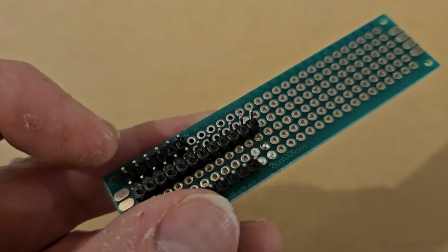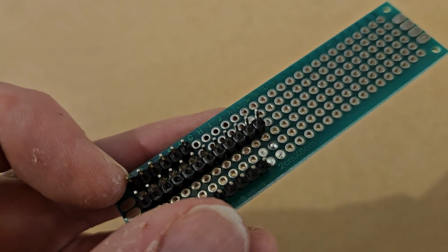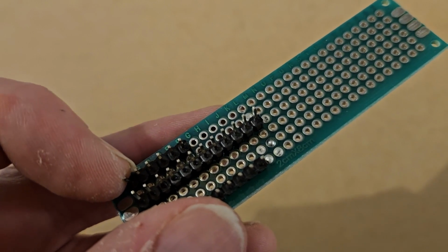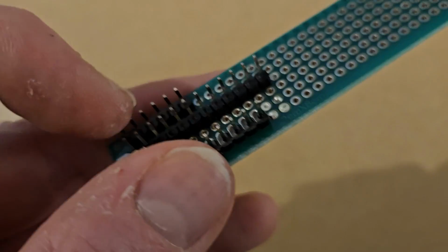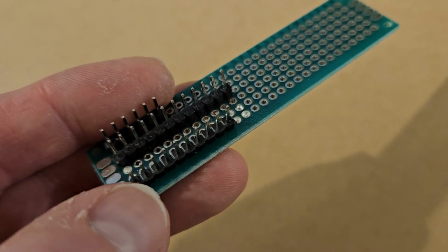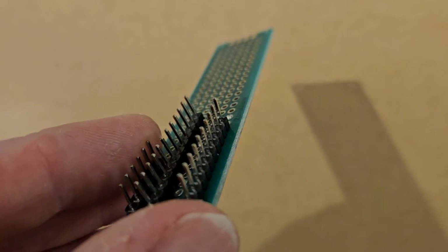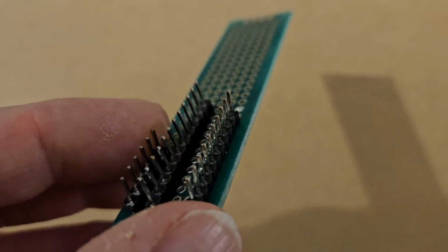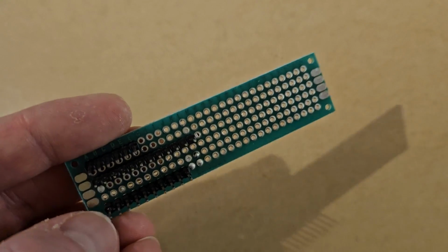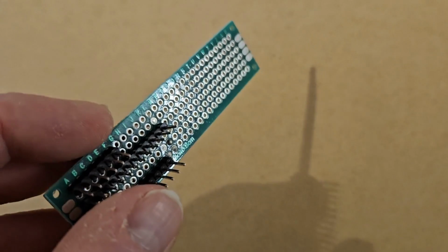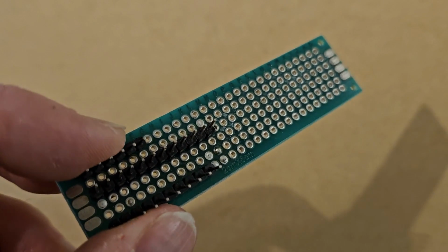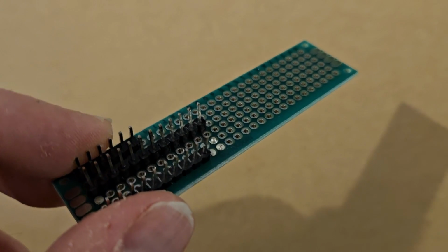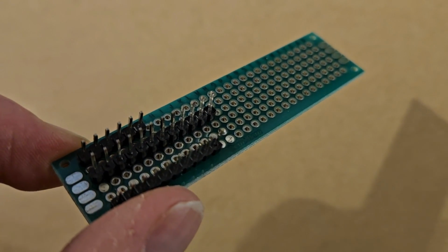And then the idea is this is the 5 volt input, so one for input, one for the screen, one for the ESP and a few spares, a run of grounds along the middle, and then the 3.3 volt shared on the bottom. And this is small enough to just screw into the inside leg of the knob box and keep itself out of the way, but fixed and steady.